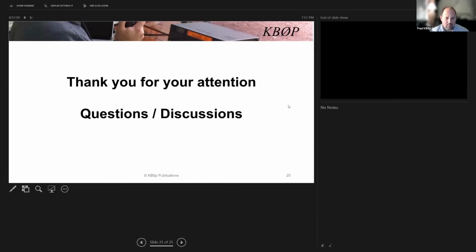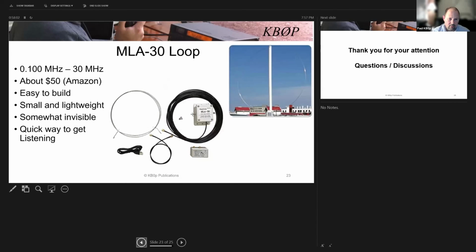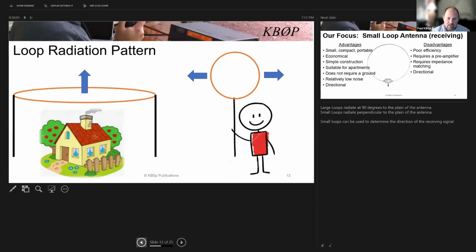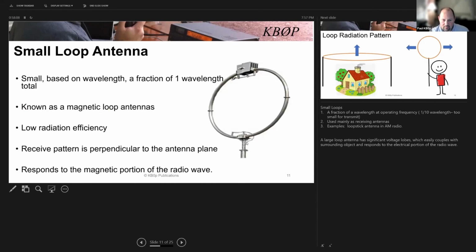Let me show you this picture because this is in my slide. And I'll just do a screen share this time. So this is what they look like right here. This is a transmitting loop actually. So I used the wrong picture for this. But here's the transmitting loop. The coax is fed down here with some sort of match. It looks more like a gamma match type situation here. And there's the capacitor, which is 180 degrees opposite of where the feed is. So exactly 180 degrees later, which is right across from the feed point, that's the high voltage node right here.